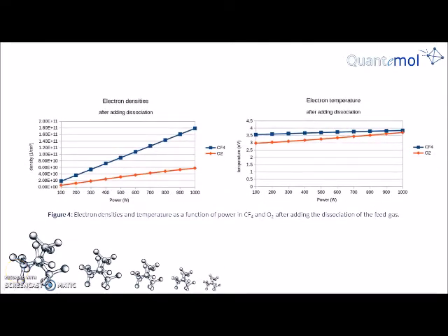It is entirely possible to have a stable simulation producing species densities in agreement with experiments, although important ionization channels are missing. In this case, the electron temperature increases self-consistently to achieve larger ionization rates. Vice versa, if loss channels for charged species are missing, the electron temperature decreases. Keep in mind to not only rely on species densities, also check the electron temperature.